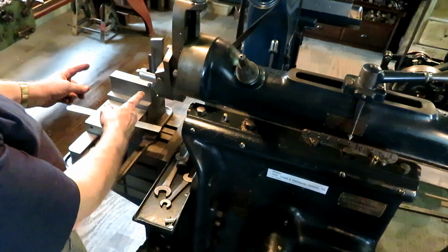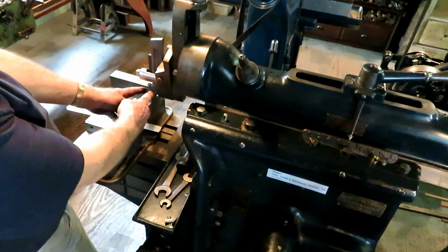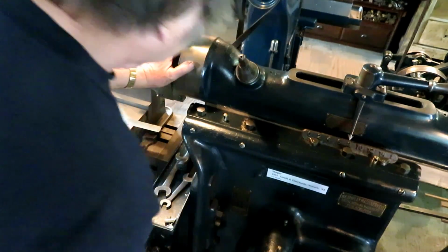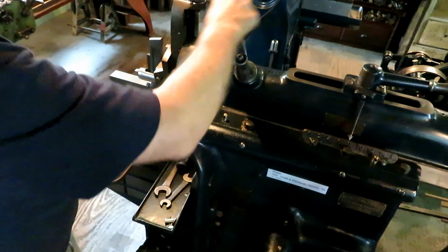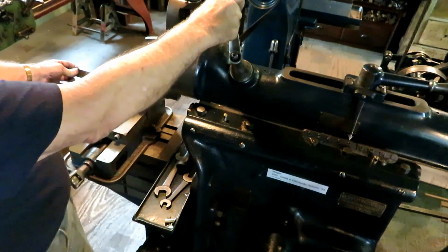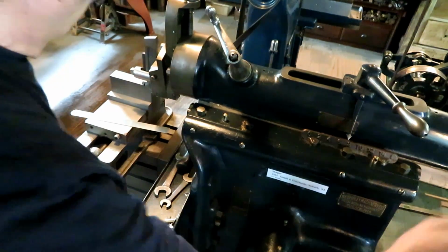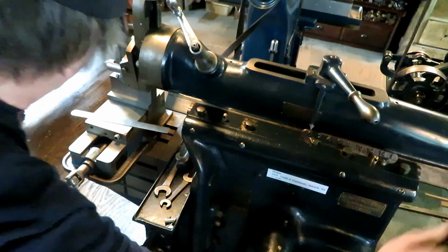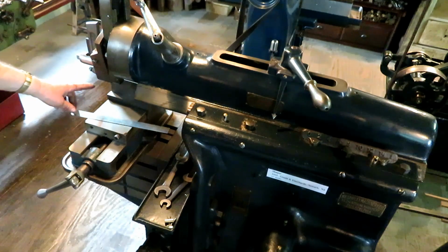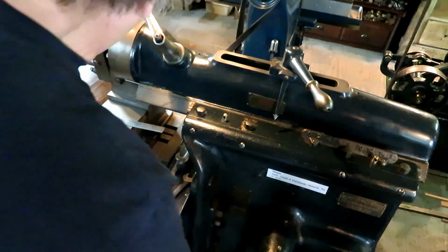Then you have to adjust where that 8-inch stroke is going to be over your piece. And I want about 3/4 of an inch off the back end. So you loosen this up, and then you can crank this up to then about 3/4 of an inch at the start. Crank it back down again, and then you can just quickly check it. So I'm overhanging by about an inch, so that's really more stroke than it needs, but it'll be fine.